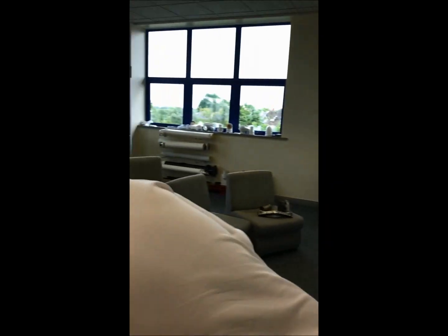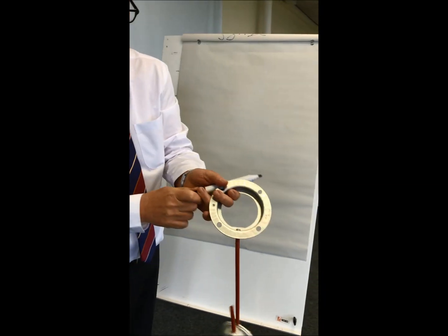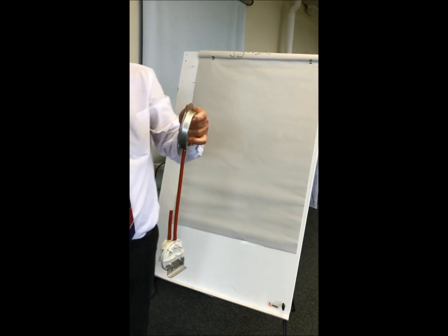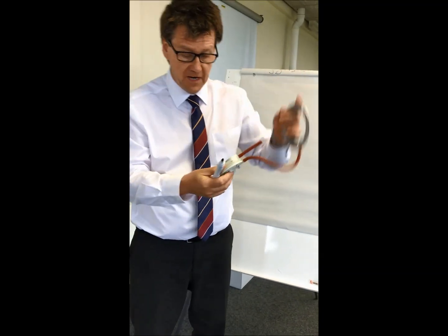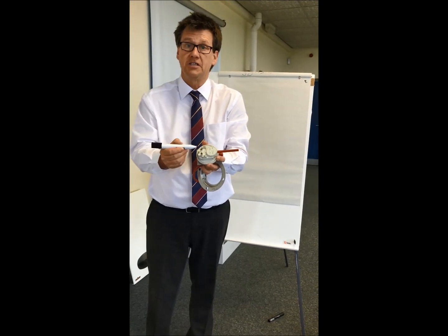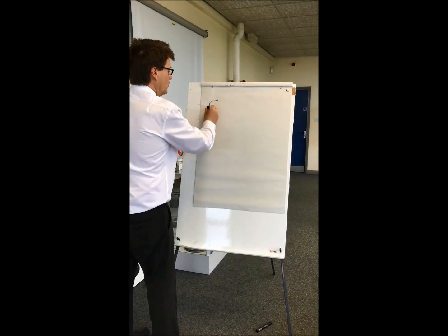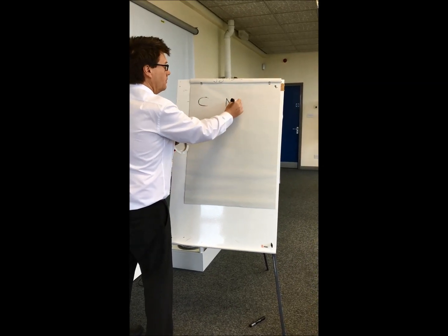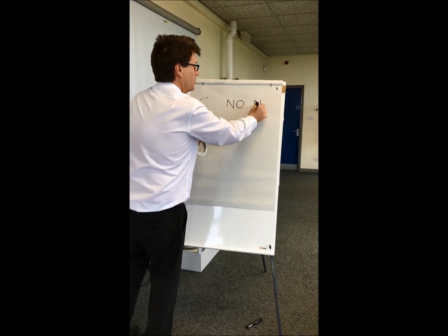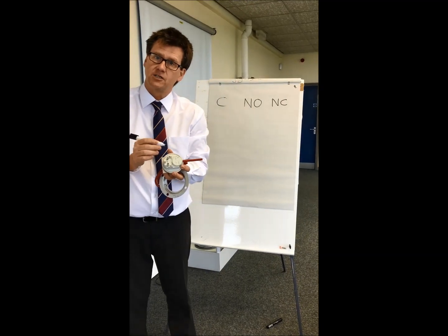I'll just swing around to this flip chart, okay? And what we've got here is an old type APS. On very old appliances, we had 3 tabs, and on those 3 tabs there were 3 wires. One of those was common, one of them was normally open, and the other was normally closed, okay? So all of those 3 tabs were actually used.